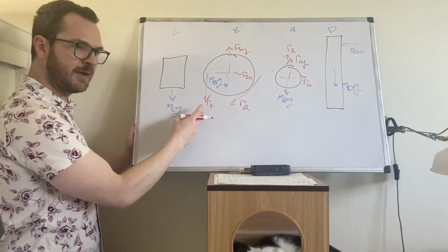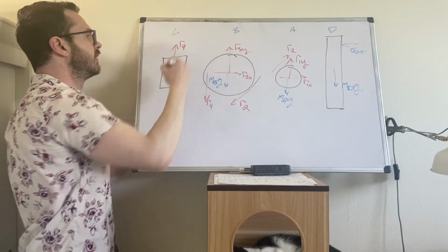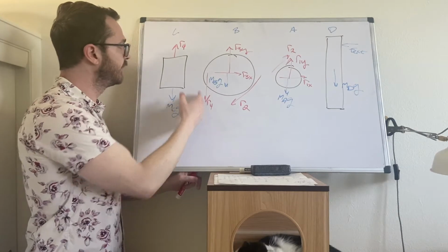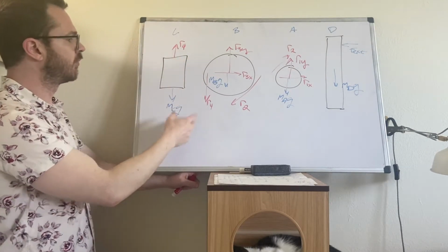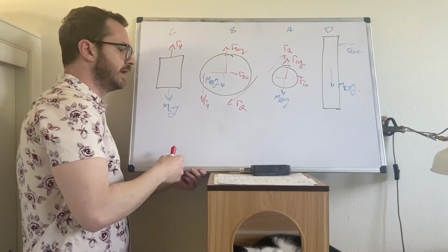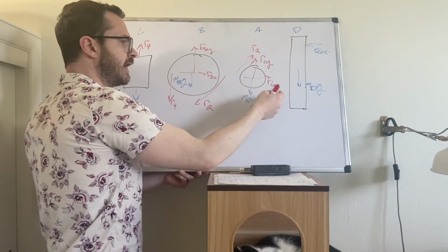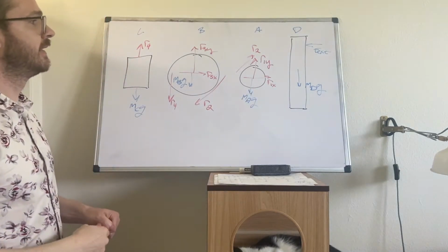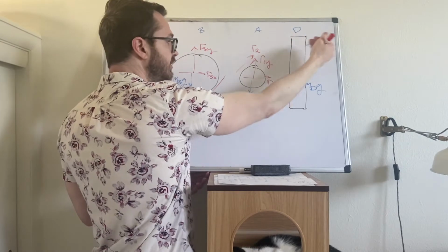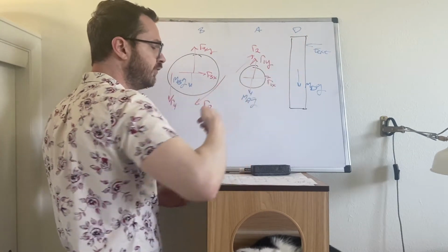The tension in the cable R4 also acts on body C. And of course, just remember we need to maintain Newton's third law throughout the whole problem: action and reaction. Okay, next, let's talk about the interface between the handbrake and gear A. So there's an external force that's pushing this thing in, which means there's a contact point between these two.